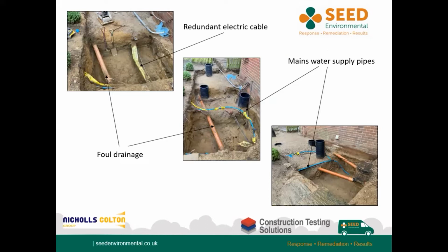Although site investigations can be planned and hotspot areas targeted for sampling, for example, around known spill areas as just shown, or chemical storage vessels, it is best to keep a dynamic view when on site. The reason for this is, within your source area, preferential pathways may be present that are only identified once you start to break ground, such as historical drainage pipes or gravel-rich beds. Contamination can more readily migrate along disturbed material associated with discrete services, and therefore may expand your area of investigation